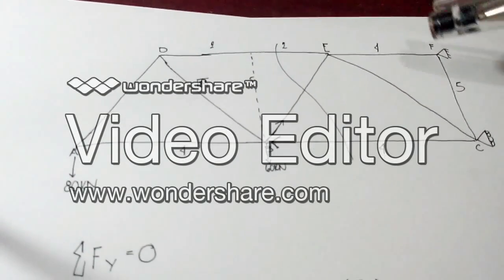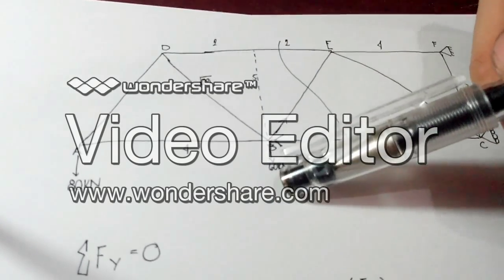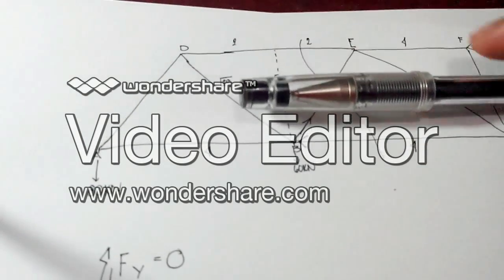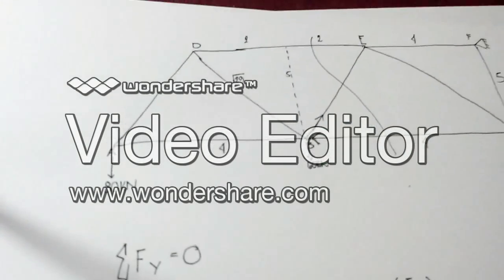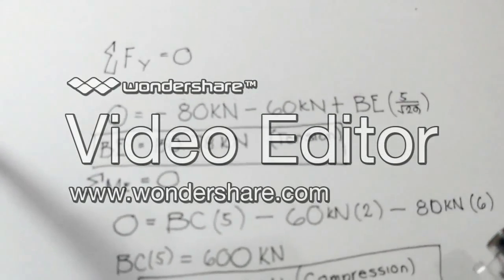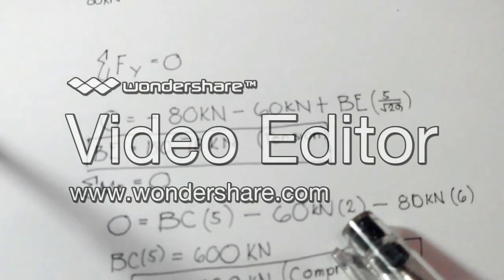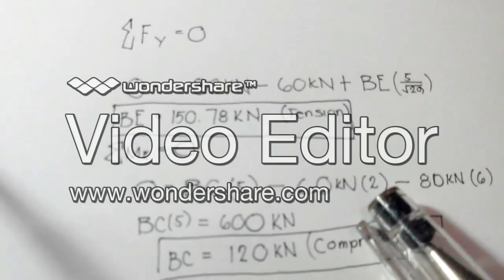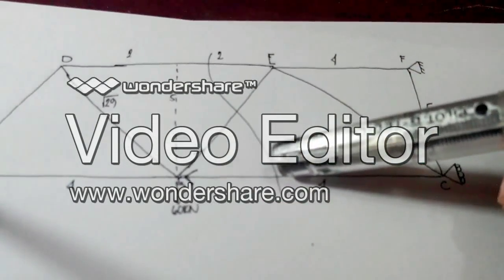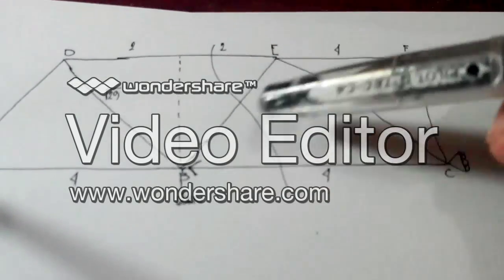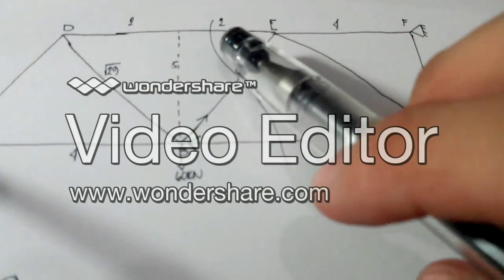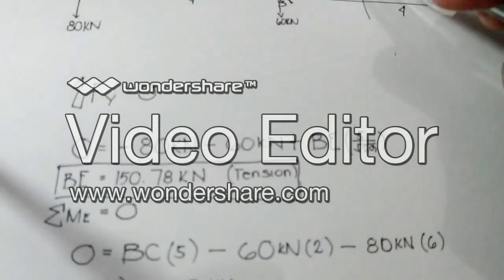The next is 60 kilonewtons, which is going downwards, and it rotates the truss counterclockwise, so it's negative. So negative 60 kilonewtons multiplied by the perpendicular distance to E, which is horizontal. This is 2 meters, so 60 multiplied by 2.